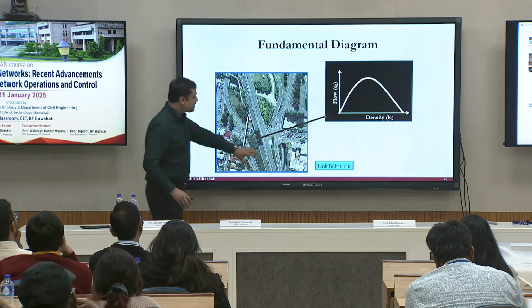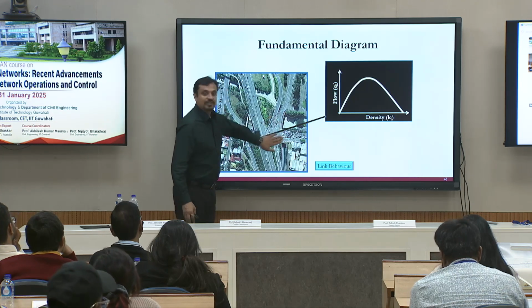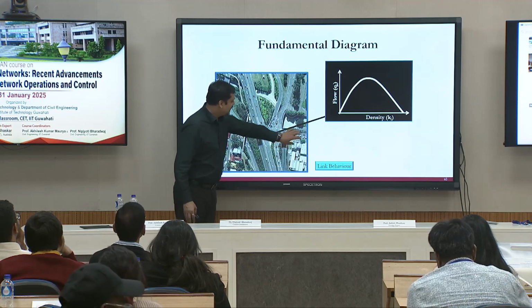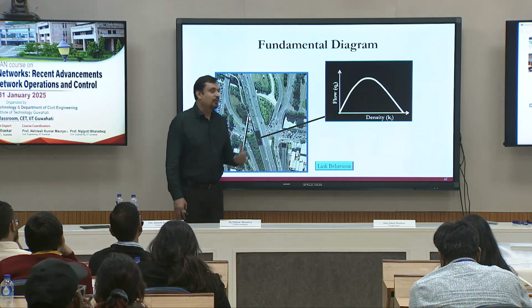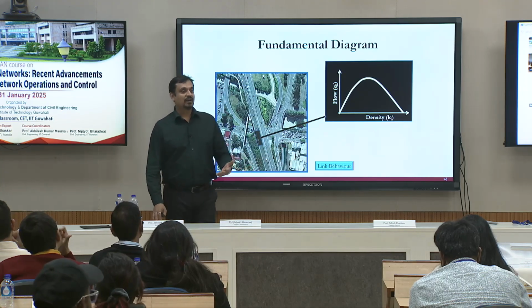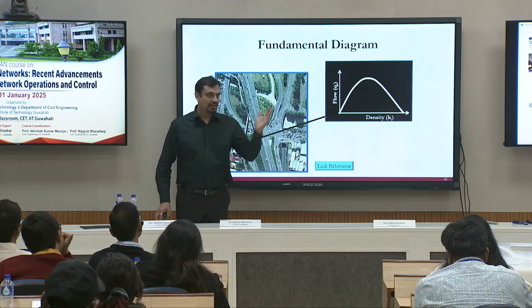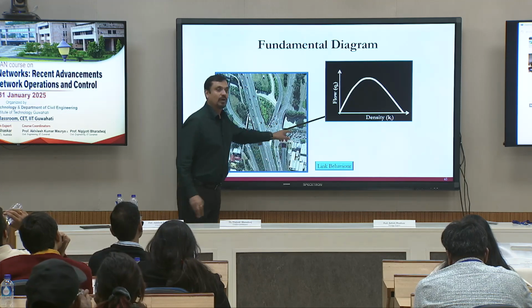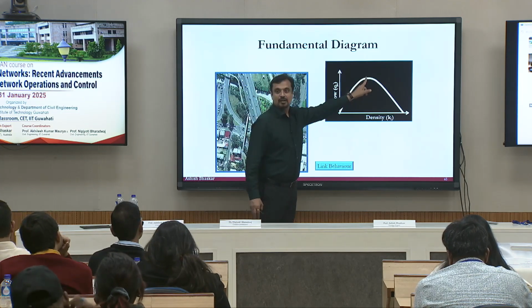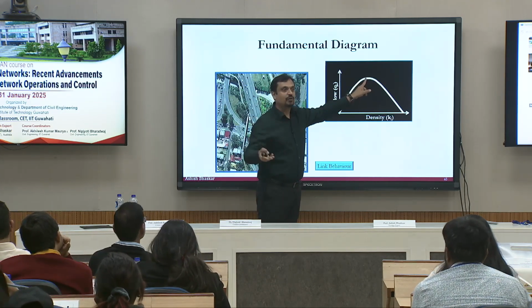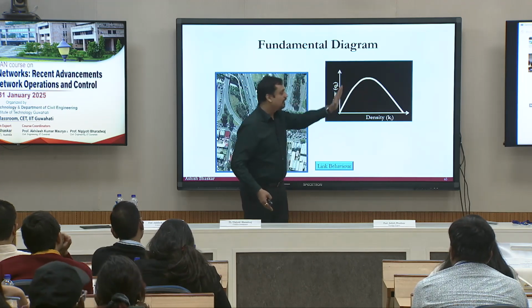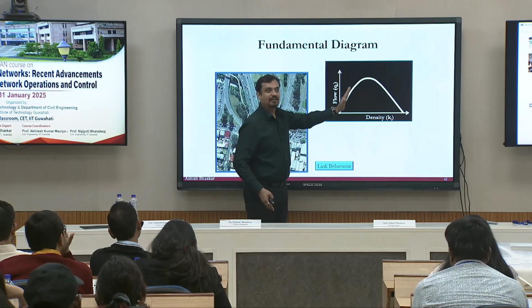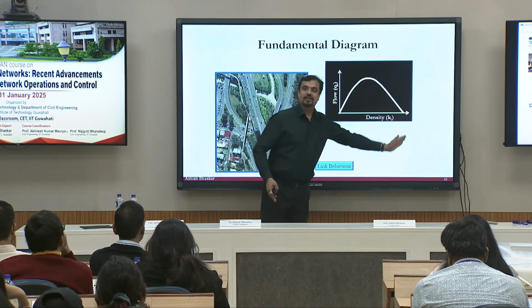No, but the thing is, imagine there was no intersection. Then this whole thing is able to flow the way it is flowing. Then the capacity, let's say for each lane, is 1800, just for the sake of argument, 1800 vehicles per hour per lane, and there's only one lane. So you will have 1800 there. But if you have given green only for 50%, that will be 900. So it will be bounded at this 900. Free flow speed will be like this, with the 900 boundary, and the other way around.